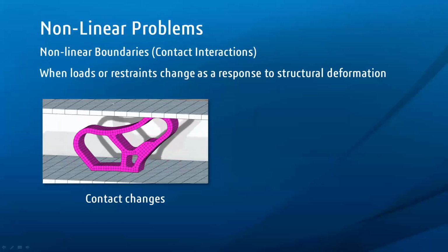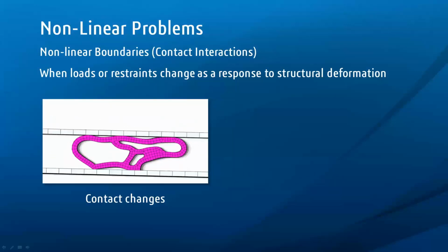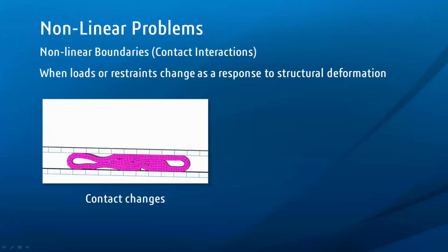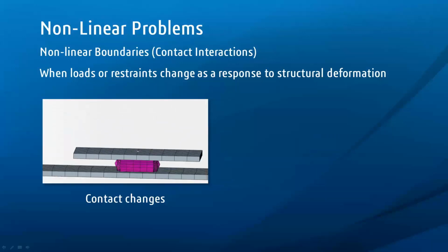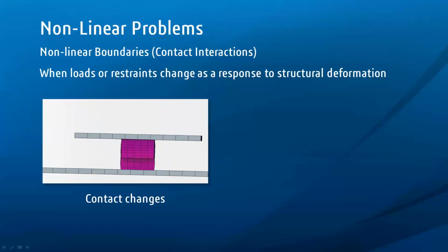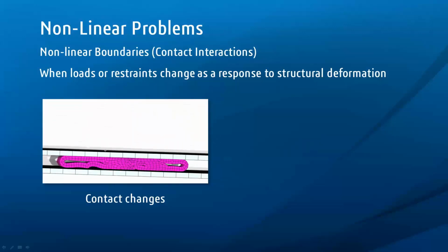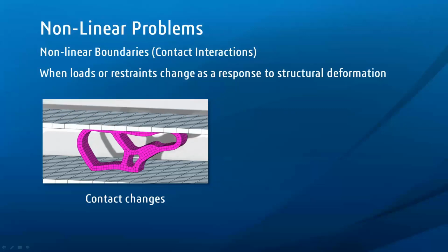For more realistic responses, we can directly define these relationships and base them on the current normal contact conditions, even incorporating rate-dependent effects. For normal behaviour, we can define conditions for self-contact, interactions between components, and sticky contact is also a possibility. In thermal or thermal structural analysis, we can define the conditions for gap conductance. All these tangential and normal relationships can be defined at a global, component, and even surface levels for maximum control.